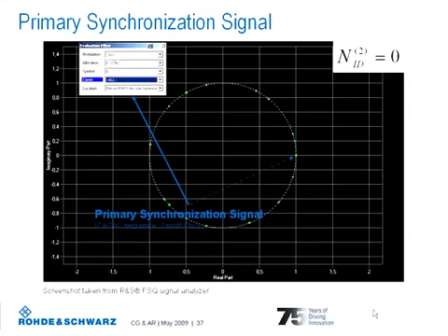With a constant amplitude, a low peak to average power ratio is achieved, whereas zero autocorrelation means a good time domain behavior. When we look at the constellation diagram of the primary synchronization signal, recorded here with the Rohde & Schwarz leading signal analyzer FSQ, we will get this result. Can we extract the characteristic of the primary synchronization signal? Yes, we can. The constant amplitude is indicated by the unit circle. The good autocorrelation can be observed by looking at each individual subcarrier carrying the primary synchronization signal.